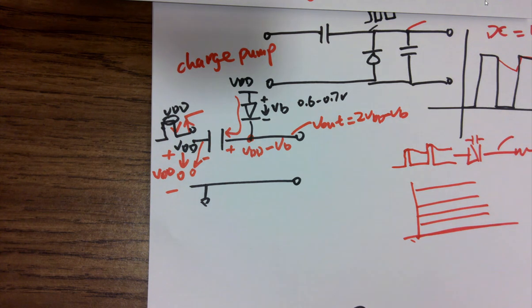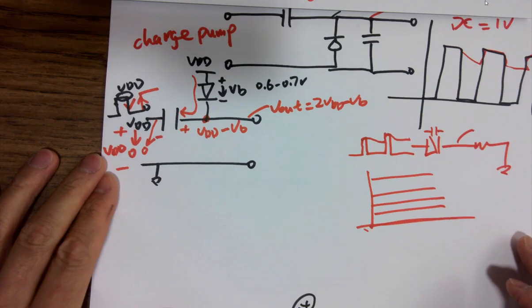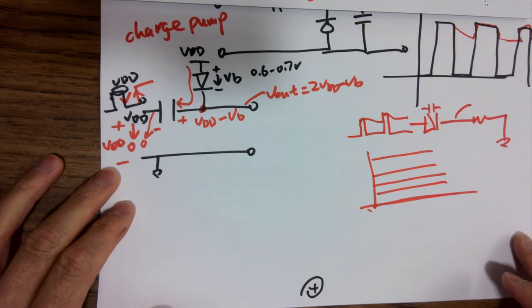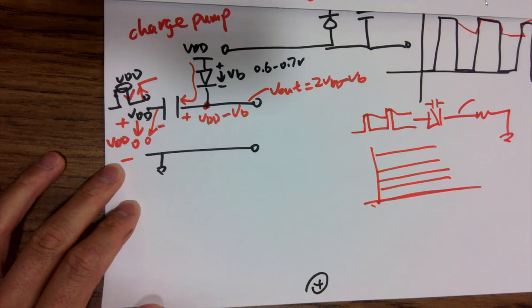Charge pump. Charge pump circuits are very important in digital circuits. A lot of times you need a charge pump to boost the voltage to a certain level in order to pass the entire signal from drain to source. So we are going to show that circuit being used for the sample and hold circuit. I believe it will be on Monday. But now I'm going to add another stage to this circuit, then we'll wrap it up.